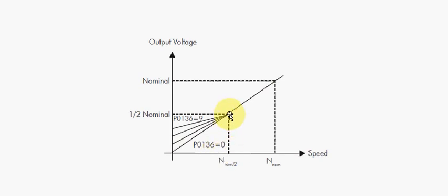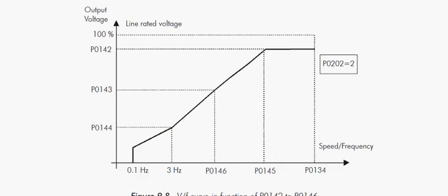And then they can also change the frequency as well here. So they can change the volts frequency ratio over here up to half the speed of the motor, interestingly enough. And here they get a little bit more fancy, where they can do exactly the same but over several points, like this.